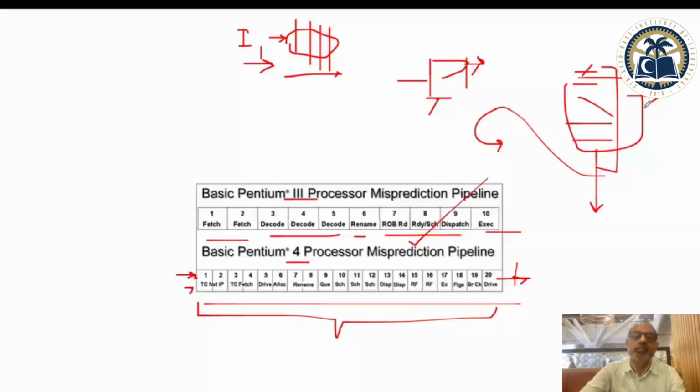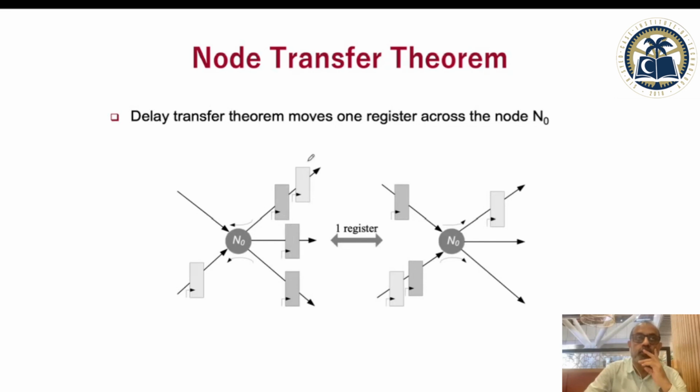So there is a lot of sophistication in dealing with pipeline hazards, and I know for sure people doing their PhDs just on dealing with pipeline hazards. You have to deal with them, especially if your logic is very complex and you have an instruction set processor, and then you have to worry about how you are going to flush the things which are in the pipeline, because now you figured out you have to do something else because of this input.